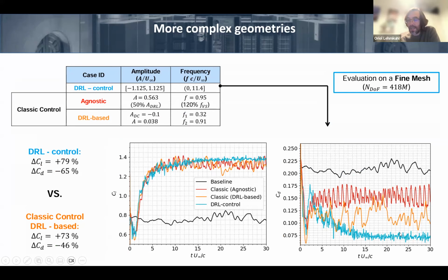And it's way better because we select less. The typical flow control strategy is to find a function that is a harmonic function, so it follows some sinusoidal type of function, and this gives some fluctuations on the drag, right? That you don't want. And the reinforcement learning finds a function that is more pushy, if you want, following more all the fluctuations of the flow and not allowing these big fluctuations to develop.